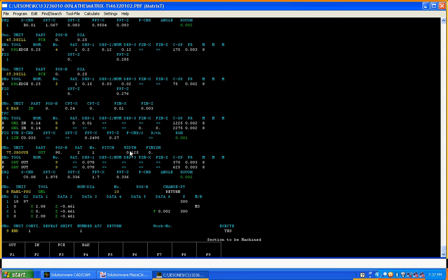So here again we have a grooving tool, but in this case you can see the width of the groove is 125. So I'm sure I was using a 125 grooving tool, and I say 130 again because this one only takes 2 decimals. And the finish here, you must have a finish allowance like 1,000 or 7/10, whatever, because if you don't do it, then it's going to give you an alarm.